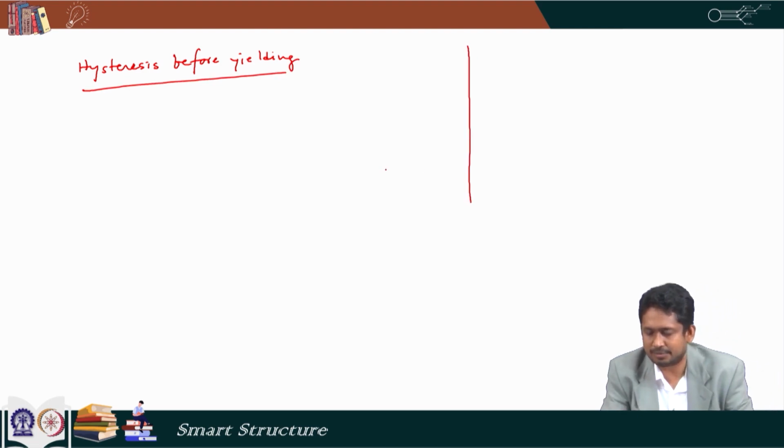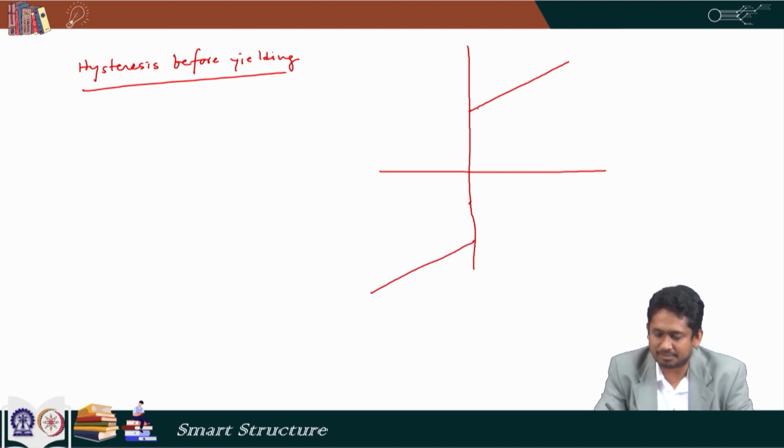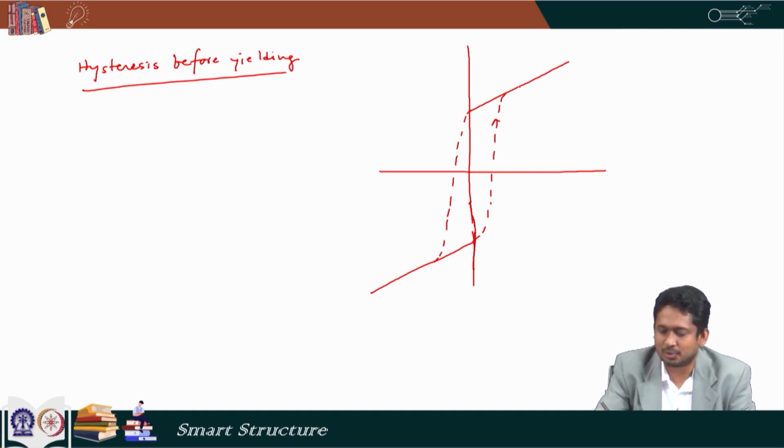If I draw the same graph, let us draw the Bingham plastic model, which is a simplified one. Even in this graph, and all these graphs are idealizations in the pre-yield behavior. Generally what happens is the material shows viscous, hysteretic behavior like this. If I increase gamma, it goes along this curve and comes back in this way. So, in the pre-yielding region there is a hysteresis,